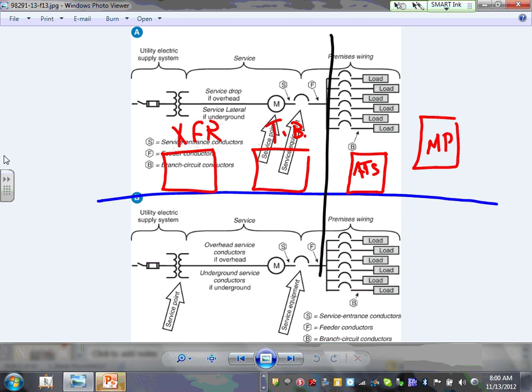Okay. You guys remember what we did? We came from here underground to the termination box, and then into this, and then from here into that, right? This is your riser that you did with Chad. Okay. Now, I want you guys to tell me, where is the service point in this case? Termination box. That's my service point. What's the name of this conductor? Who owns and operates this conductor here? The utilities. So they have to put their conduits and wires.